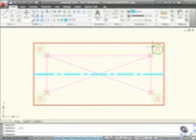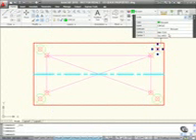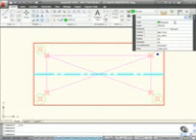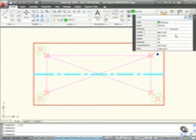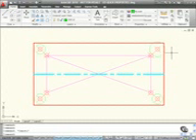And then when you select an object, there you go, there's my circle settings there. Look, as you can see, there's more lines of information there. When I move away, it displays the minimum 5 lines. When I move the crosshair over it, it gives me more information. So as you can see there, if I change the radius there to say 30 and press enter, that updates and my circle gets bigger. When I close the Quick Properties palette there, you can actually see that my circle is bigger.